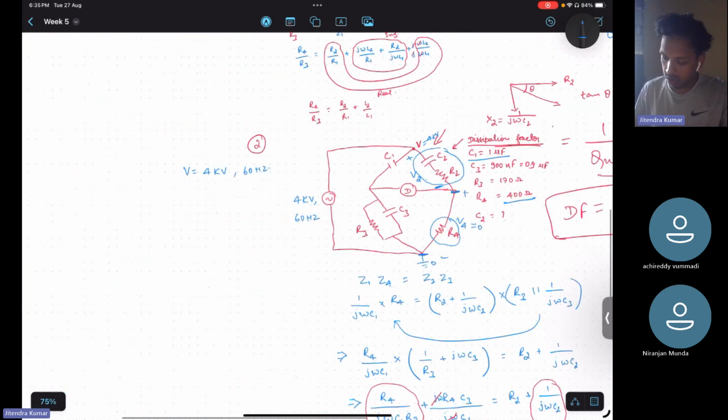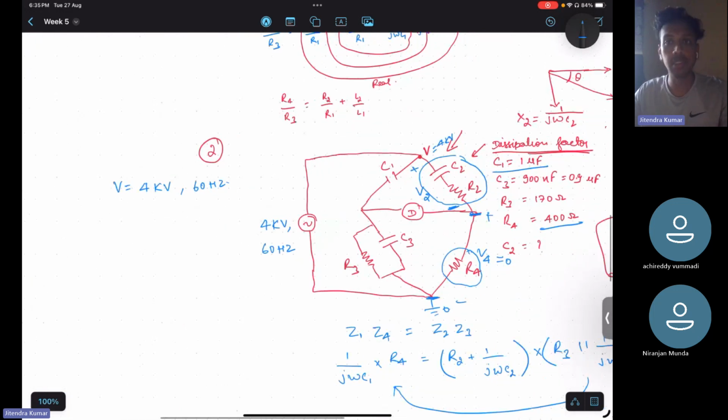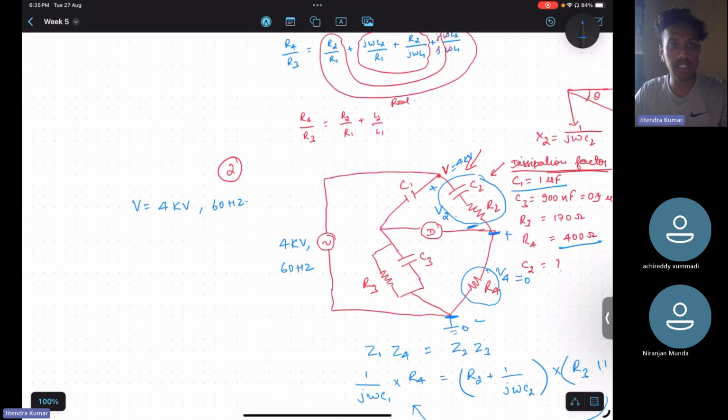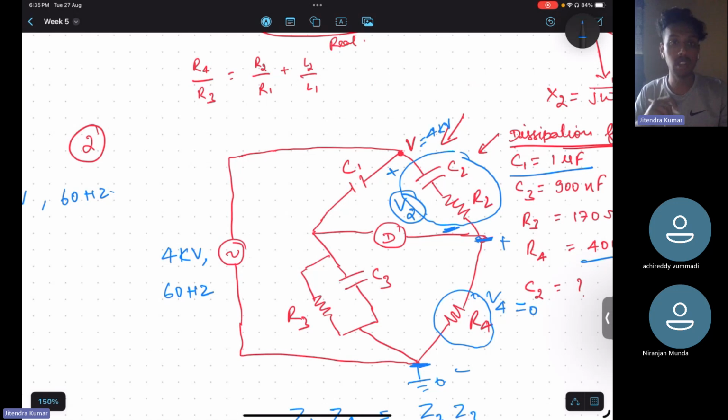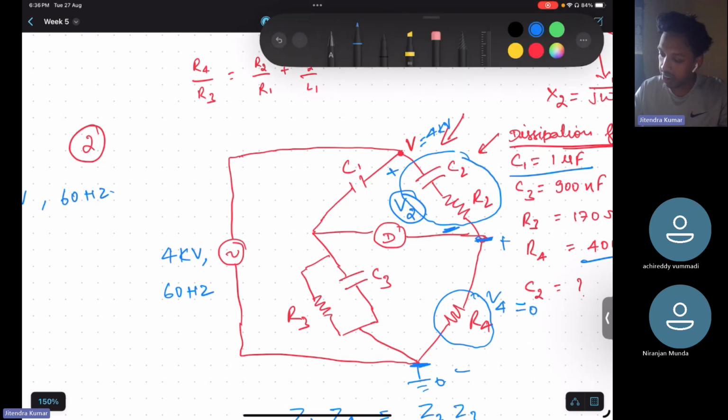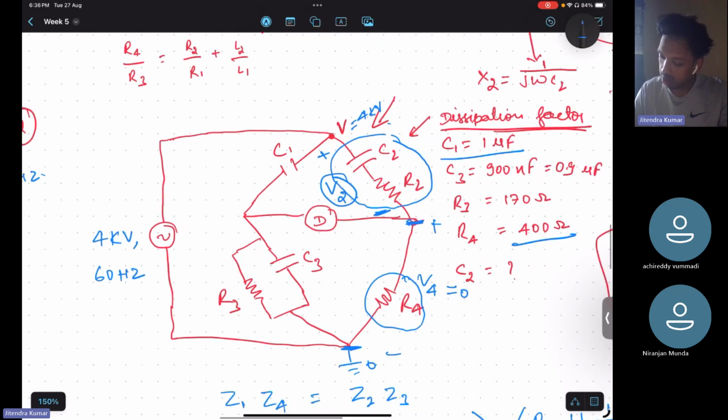So yeah, the next problem was that we needed to find out the voltage across this branch. The concept of why this kind of circuit is generally designed, which I was telling earlier, is that a very minimum voltage drop should happen at V2. When we are tuning it, C2 and R2 can be tuned in such a way that we do not get proper balancing, and at such a high voltage it is very difficult to balance the bridge. In such a case a very high amount of current could flow through the circuit.